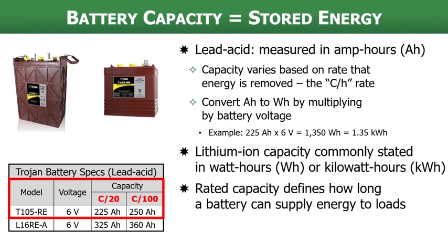Keep in mind also that we don't want to use the entire capacity of the battery in most cases because that will have a negative impact on the cycle life or the lifespan of the battery, especially when we're talking about lead acid batteries. Some lithium ion batteries can be discharged to 100% depth of discharge using the whole capacity of the battery. We're going to need to read the manufacturer's literature and see what kind of an impact that's going to have on the lifespan of the battery.